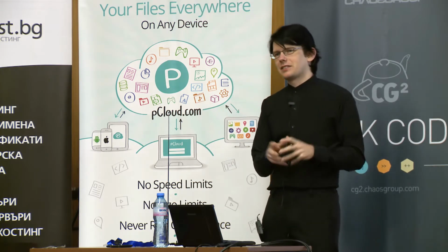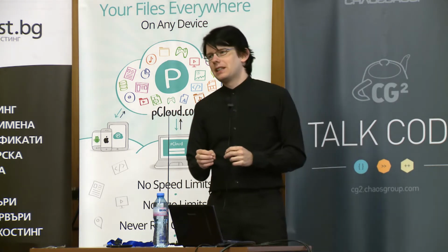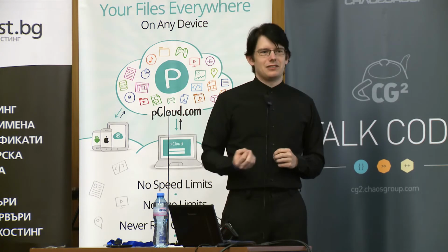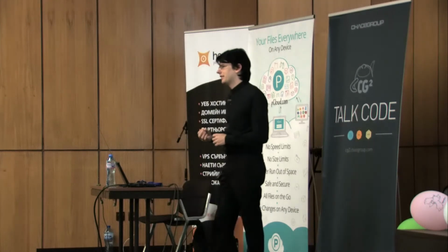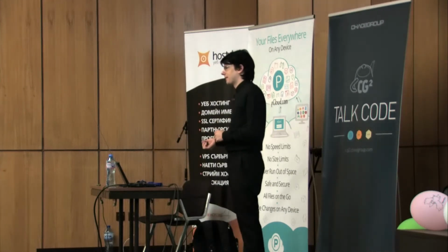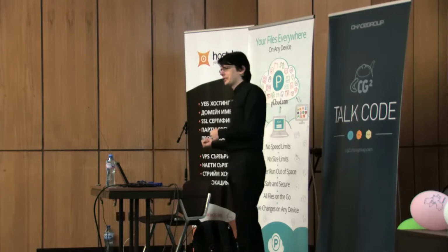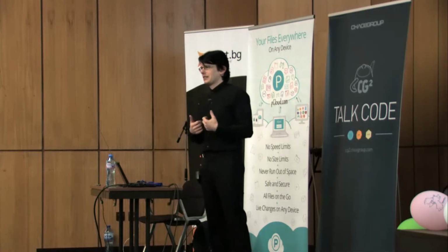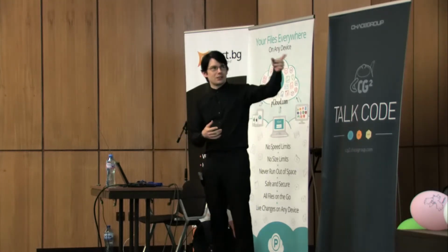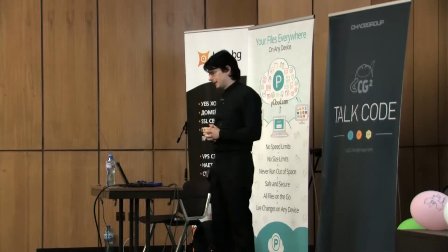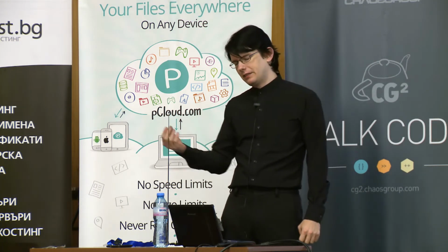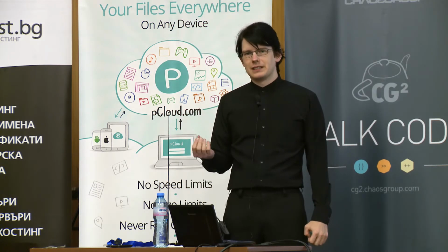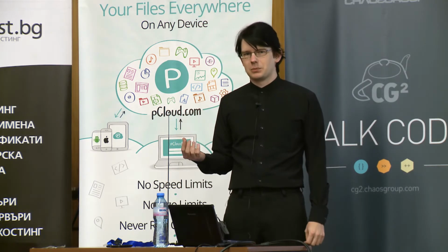And it turns out that Realtek put a special mode in this chip that allows you to deactivate all of the TV receiver and instead send the raw samples of the ADC over USB into the PC. And then you can implement your receiver in software on the PC. So what some of the vendors who built these USB sticks did is they activated that mode, and then you get the raw samples of the baseband into the PC, and in the Windows software, they implemented a DAB receiver for digital audio broadcasting.